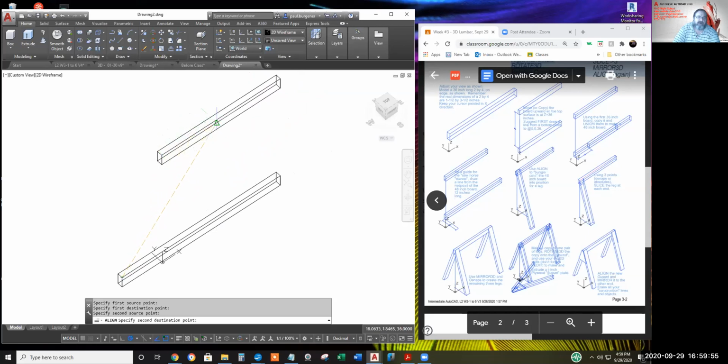But I'll slide up from the end point and Osnap on the midpoint. Notice there's midpoints of different edges close together. So double check you're on the proper midpoint.